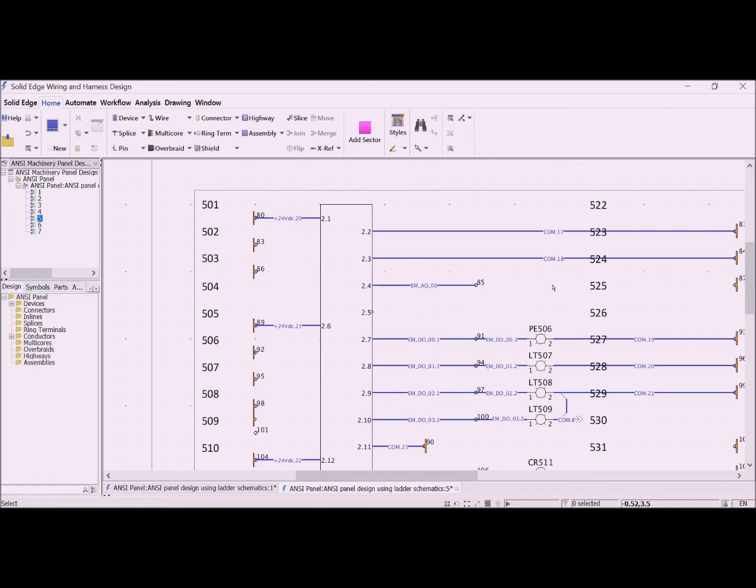As the symbol we want to use is already on the screen, we'll reuse existing data with a copy and paste action. A new enhancement sees the graphics become a ghost, which moves with the mouse. This provides better guidance for the user and increased accuracy on placement. The numbering on the pilot light is automatically assigned to represent where it has been placed on the ladder. As the device is moved around the design, the name of the device updates accordingly.